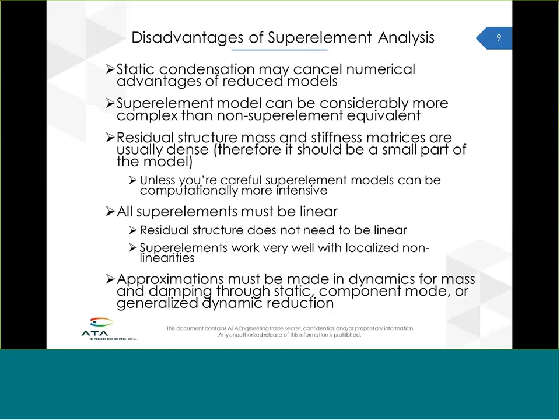And then you do have to make approximations with dynamics for mass and damping because of the modal component mode approach. Anytime you're solving for modes, you always have to decide how high of a frequency to go to or how many modes to include. But that's no different than superelements.